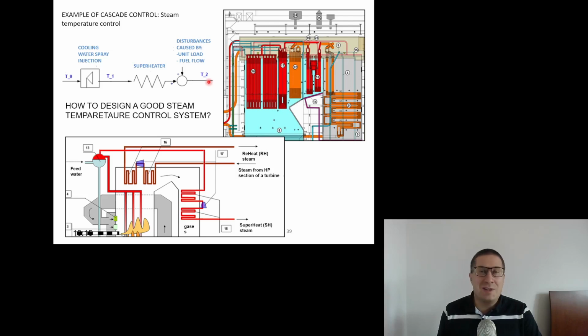So we are risking. If the temperature is too high, like 550, 560, we'll see alarms related to the heating surfaces that the temperature is too high and it can damage the boiler. On the other hand, if it's too low, the efficiency drops. So 540 is, let's say, the optimal temperature for a boiler with a drum. It's of course higher for supercritical boilers.